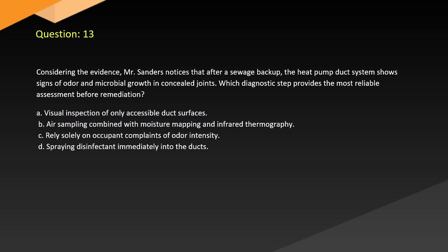Question 13. Considering the evidence, Mr. Sanders notices that after a sewage backup, the heat pump duct system shows signs of odor and microbial growth in concealed joints. Which diagnostic step provides the most reliable assessment before remediation? A. Visual inspection of only accessible duct surfaces. B. Air sampling combined with moisture mapping and infrared thermography. C. Relies solely on occupant complaints of odor intensity. D. Spraying disinfectant immediately into the ducts.